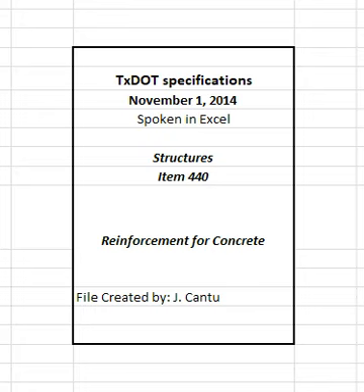2.6 Welded wire reinforcement. Provide welded wire reinforcement, WWR, conforming to ASTM A1064. Observe the relations shown in Table 2 among size number, diameter in inches, and area when ordering wire by size numbers, unless otherwise specified.